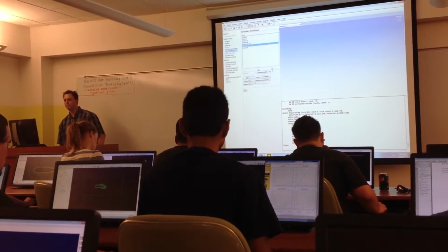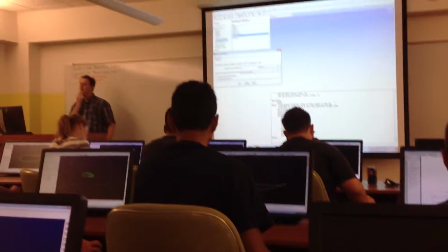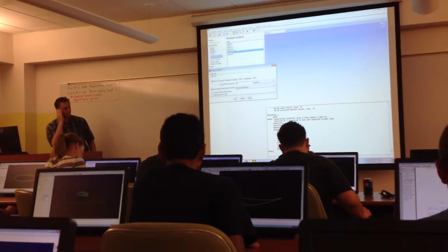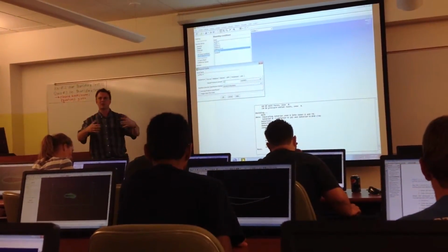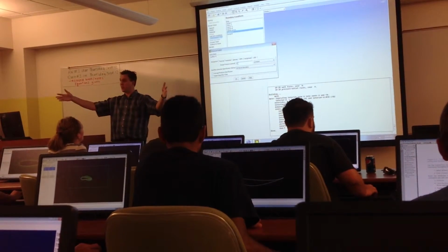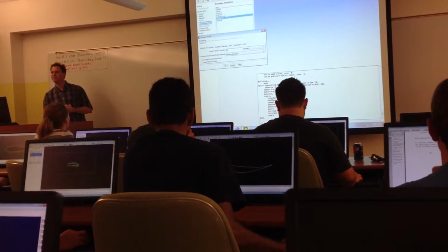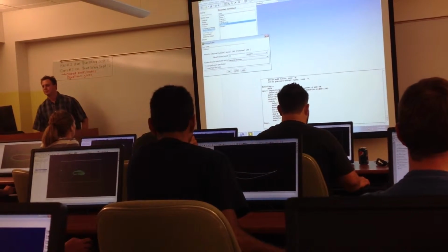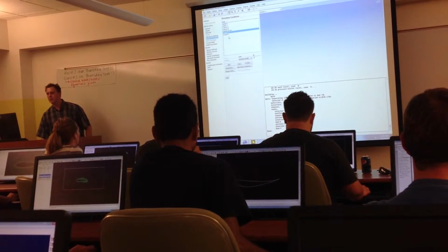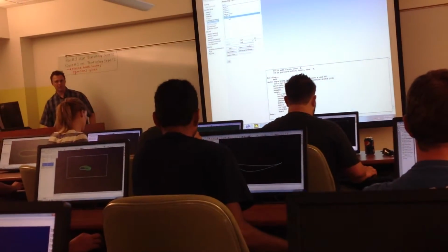Next, outflow. The gauge pressure. Whenever a flow leaves a wind tunnel, it's going to quickly equilibrate with the pressure that's surrounding it, the atmospheric pressure that's outside of the tunnel, which is a gauge pressure of 0. So the default is fine. And as it turns out, the absolute pressure actually doesn't matter at all in a computation like this.